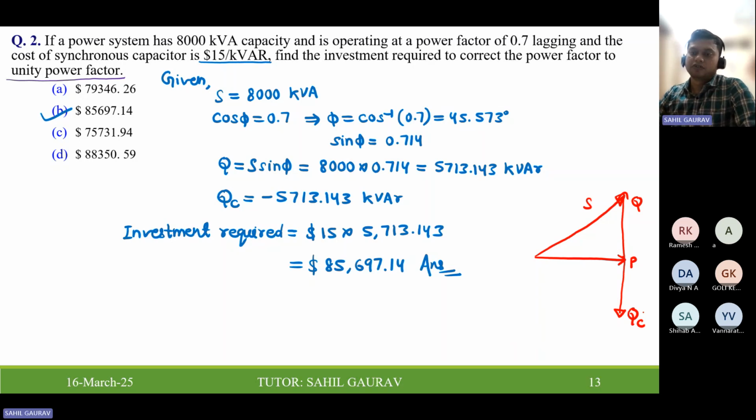So the magnitude of QC equals Q. It is given that unity power factor, that's why whatever the reactive power of load, that is being compensated by the capacitor.